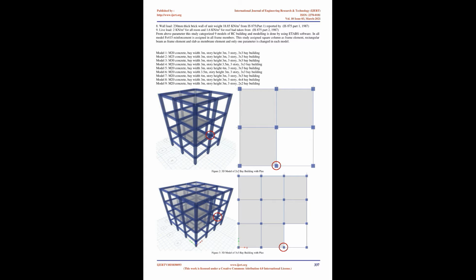During horizontal earthquakes, moments and shear forces acting on the beams and columns of the frame building result in internal vertical and horizontal forces on the face of the joint core. The internal forces produce a resultant acting in the joint core, either a diagonal tensile or compression stress. Diagonal tensile stresses and compressive forces result in cracking and crushing of the concrete core.